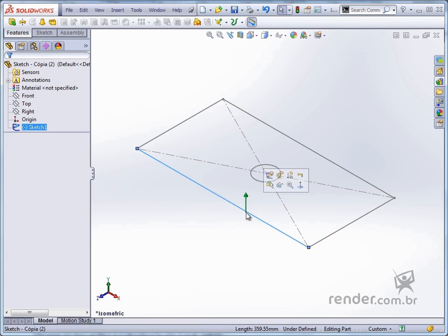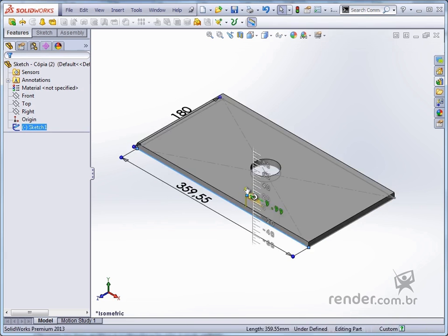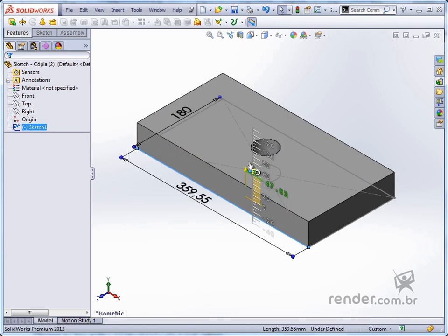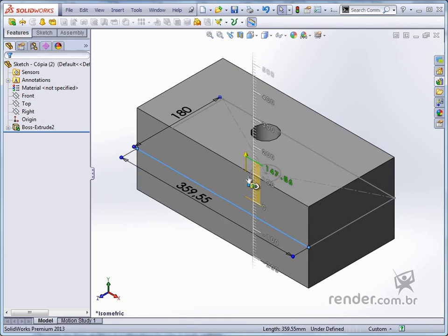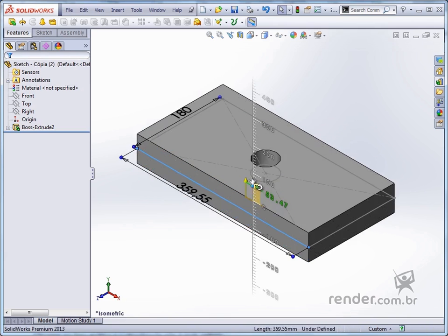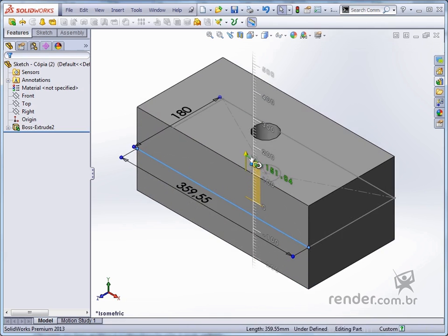When clicking on an edge of the sketch, note the arrow shown. By dragging this arrow, we automatically create a solid. By holding down the letter M of the keyboard, the extrusion is created for the final condition midplane.